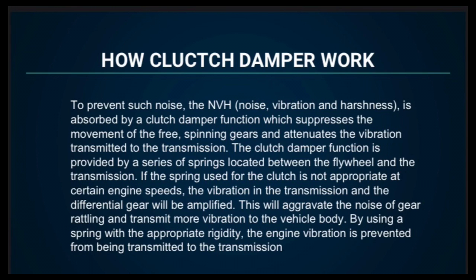If the spring used for the clutch is not appropriate at a certain engine speed, the vibration in the transmission and the differential gear will be amplified. This will aggravate the noise of gear rattling and transmit more vibration to the vehicle body. By using a spring with the appropriate rigidity, the engine vibration is prevented from being transmitted to the transmission.